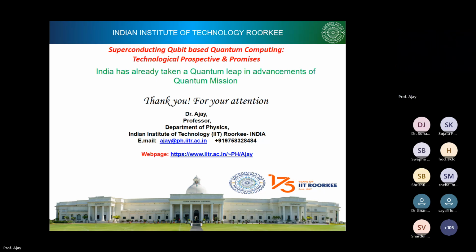It is because of the Kronig-Penney model that you have been taught by now that there can be reflection of electrons from the zone boundary, and there is a band gap. And the band gap in the semiconductor we are using is an indirect band gap. I think you will agree. So the top of the valence band and the bottom of the conduction band are not aligned. They are not at the same K vector. They have some shift.